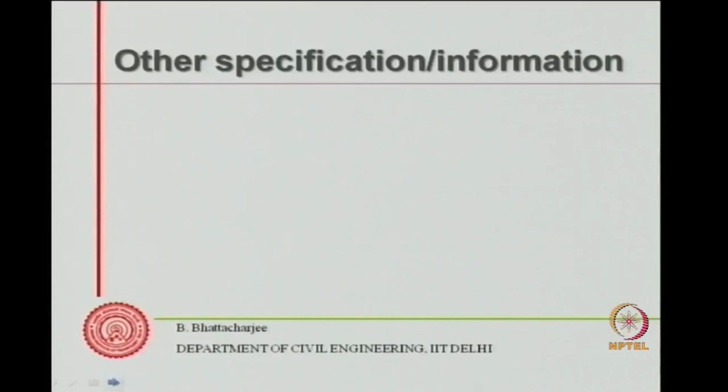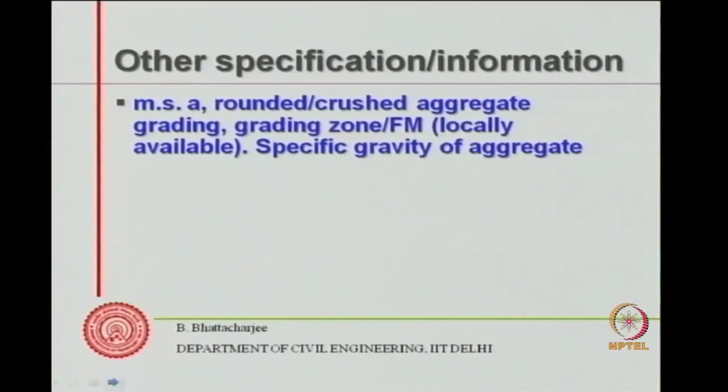So at the moment we are trying to look at the mix design. So this is how we specify the concrete, and once these specifications are available, some more additional information may be needed. These additional informations are nominal maximum size of aggregate,